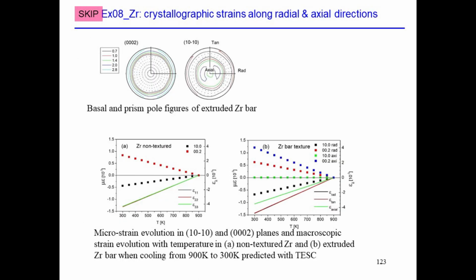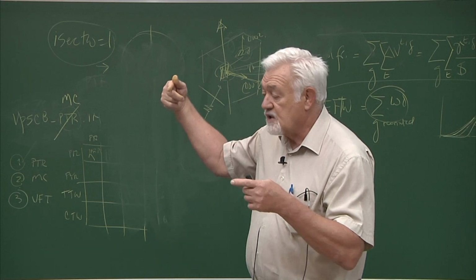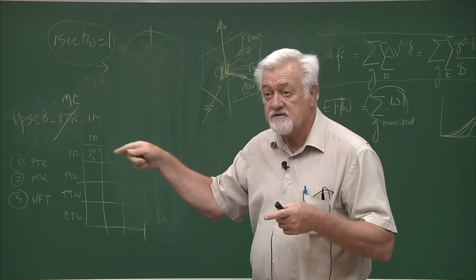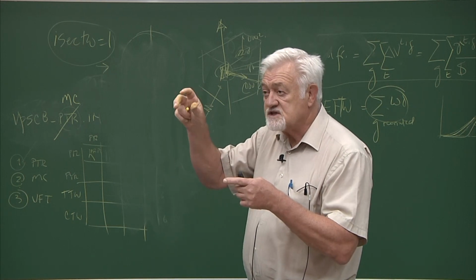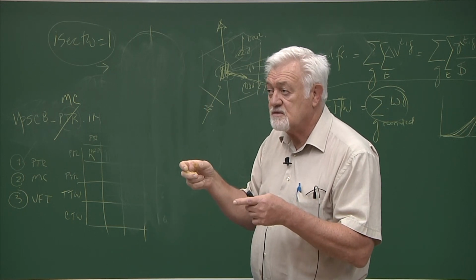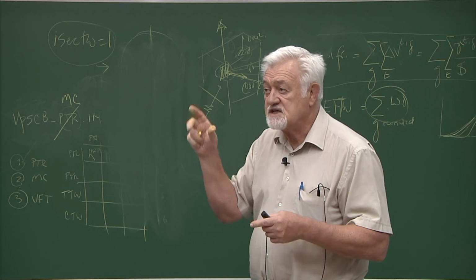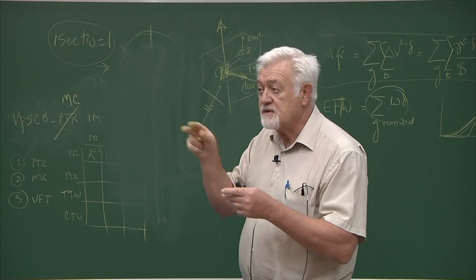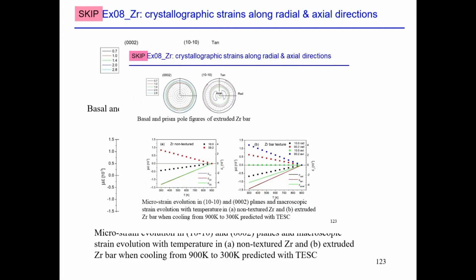And so you are really measuring subsets of grains inside your crystal, depending on how you orient your sample or where the X-rays or the neutrons are coming from. You are choosing only subsets of grains in your material to see what is the crystallographic strain perpendicular to specific crystallographic planes. So that information is very valuable.